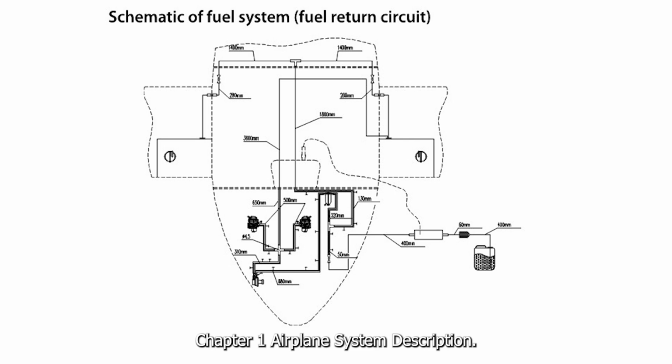Chapter 1. Airplane System Description. Fuel System. Fuel system comprises a vented fuselage fuel tank refueling aperture on top left side of the fuselage behind the wing. Fuel tank is located inside the fuselage with a fuel shut-off valve inside the cockpit. Fuel hoses are protected with glass and silicon rubber, and fuel system features fuel return circuit into the fuel tank.